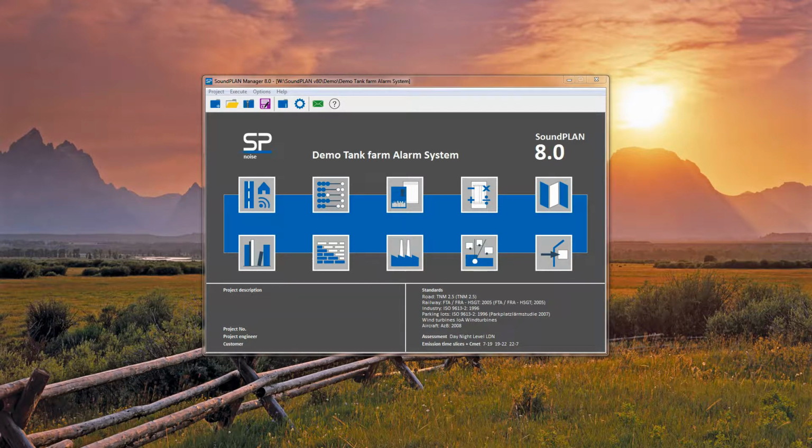And of course, with any changes in the geometry, the power level has to change to adjust because the distance effect, if you're in the near field or far field, is of course very different. So this is a good way of calibrating your input and making sure that you're getting the right answers or that your source definition is correct.